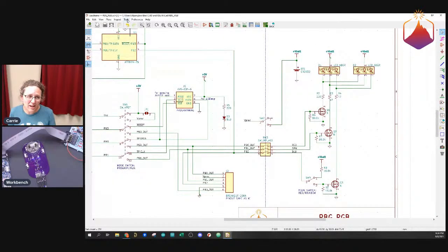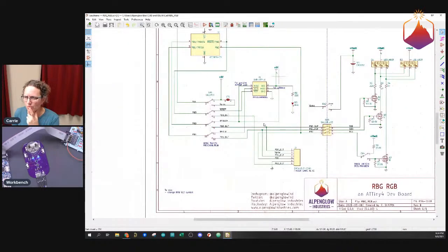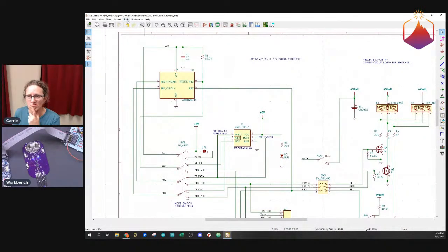So I haven't attached footprints yet to any of these. I'm guessing that's probably going to be part of my netlist. It didn't give an error, but let's see about attaching footprints maybe. That is separate, there we go: assign PCB footprints to schematic symbols.